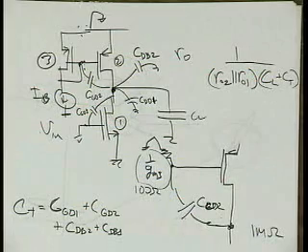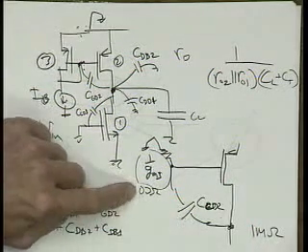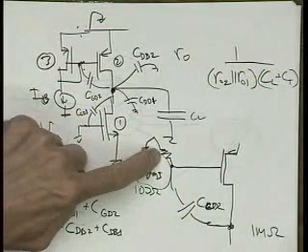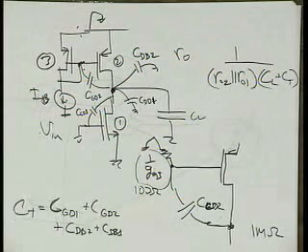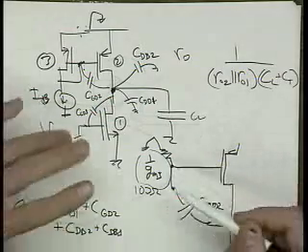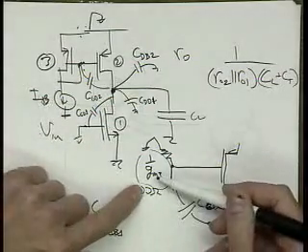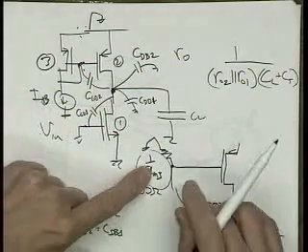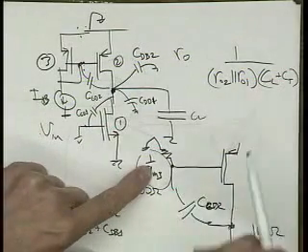So like 10 microamps is large. Well, it's not the current so much; it's the resistance that you end up with, the 1 over GM. So it's the size of this transistor as well, right? GM's proportional to the W over L and the current, right? So you have to figure out, so this is just becoming an issue here of what sets your current. Just make sure that you size that transistor. You want to make it small, okay?